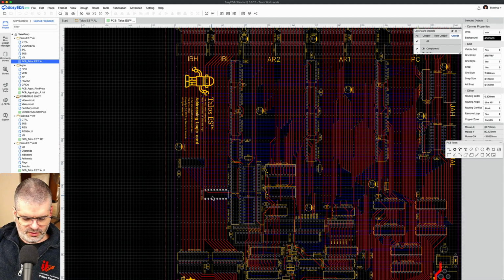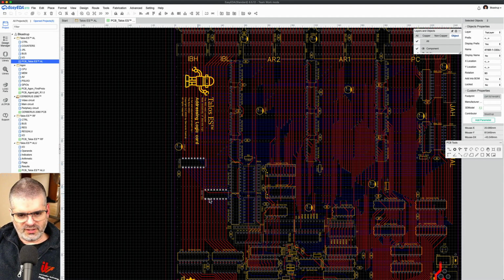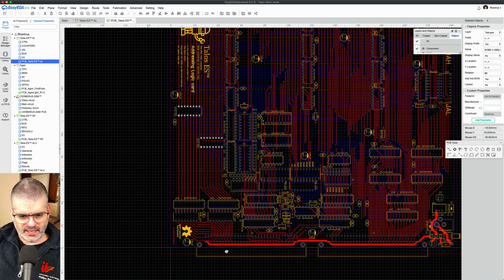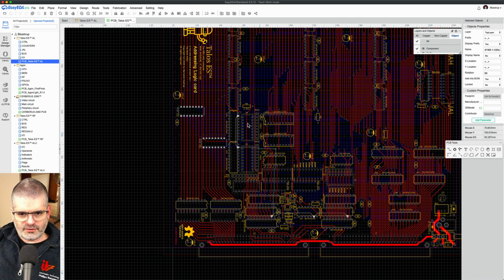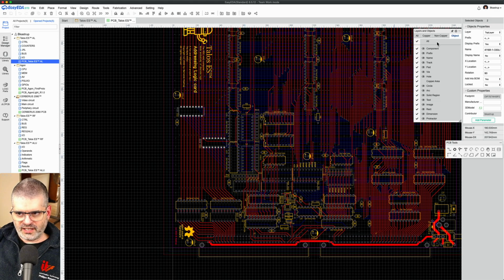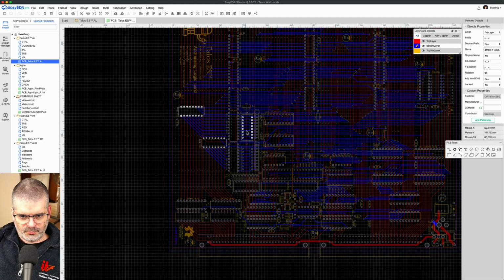I am using these two resistor networks here. They are 33 ohm. I'm using them in series after we select whether the local bus here on top is connected to the internal bus via the backplane, which comes from here, or from the dip switches, which are there. So after the selection is done, you can see here the blue lines of the dip switches go into the inputs or the low side of these resistor networks. So do the internal bus signals from the backplane. So after the resistor networks, there has already been a selection: do the bus signals come from the backplane or from the dip switches?